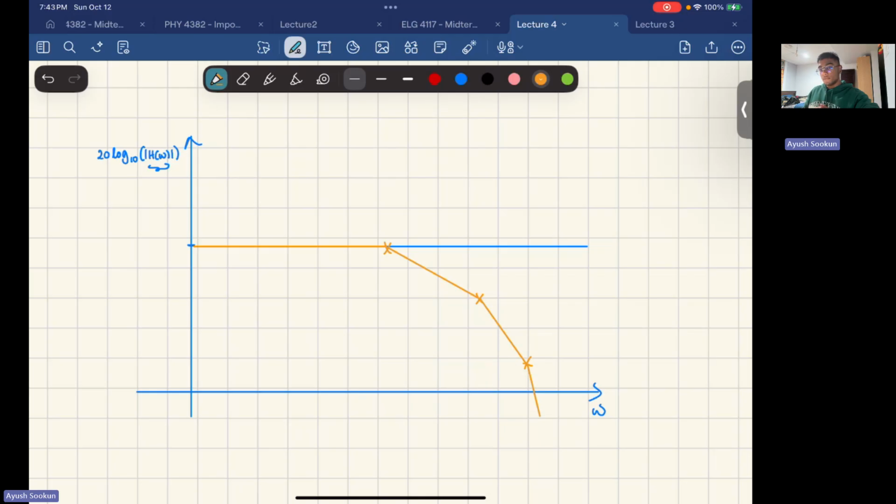What's responsible for these poles, you might guess it, is capacitors. You can do AC analysis with the AC hybrid pi model with the capacitors in there, same thing with the BJT, and then write Vout over Vin. However, that is not efficient, and mistakes are going to be made. It's terrible to do AC analysis with capacitors. So we have methods we can implement to make our lives easier. We need to find those poles. There's something called the pole identification technique, and to be able to apply it, we need Miller multiplication of capacitors.